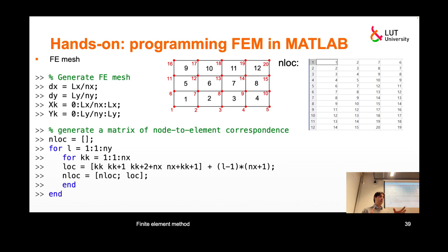You remember the coordinate transformation to local axes, it's tied to coordinates, and even if you don't do this transformation, you still need to know the coordinates of nodes to be able to do your approximation. So I will be storing a matrix of x coordinates and a matrix of y coordinates in this form.